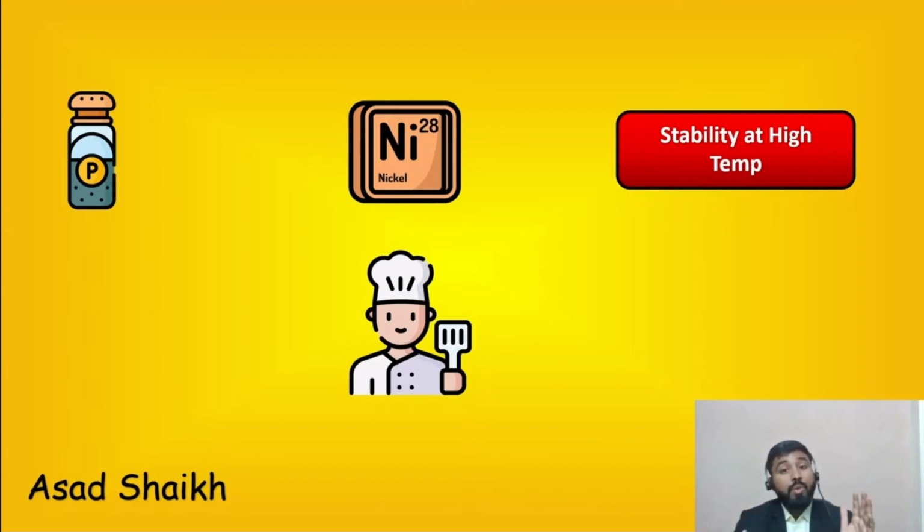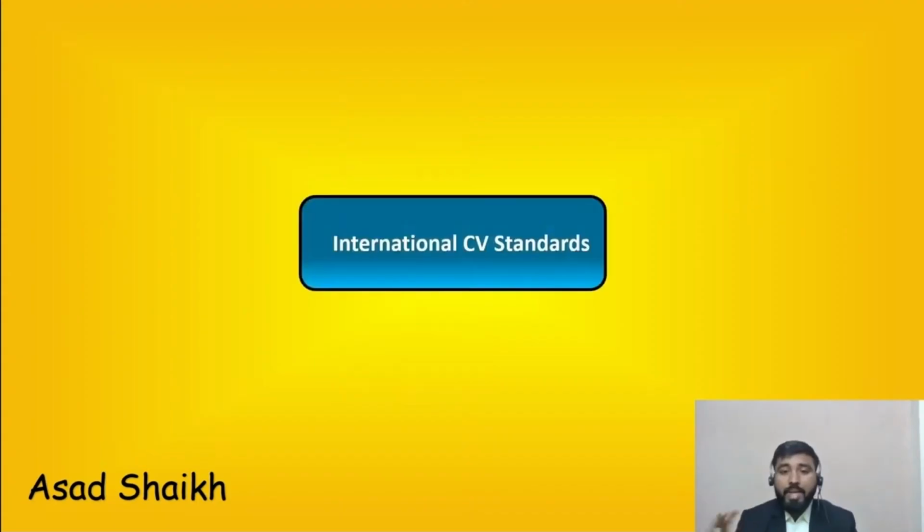If not possible, only then you start to go for bellows. It is the worst case scenario. If nothing works, and your fugitive emission is extremely high, which is class A, then only you should think of a bellows seal valve. I'll just quickly wind up by giving you at least the basic international standards.